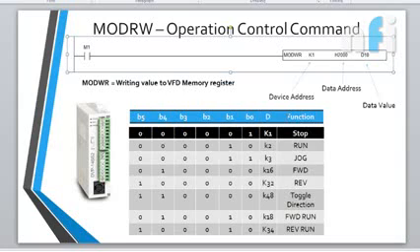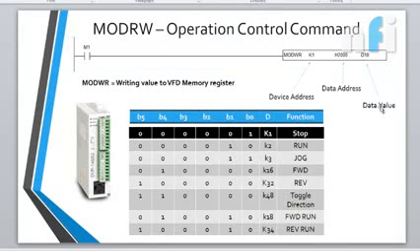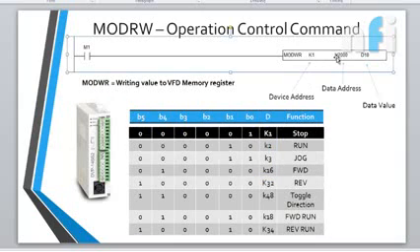So what the PLC is doing is, PLC is writing the value of D10. D10 is the data value. Whatever value will be here, it will be transferred to H2000. Now it is up to the manufacturer. These values, if you see here, K1, K2, 34, are defined by the manufacturer of my VFD, that if I put K1 into H2000, drive will stop. Okay, this is already defined.